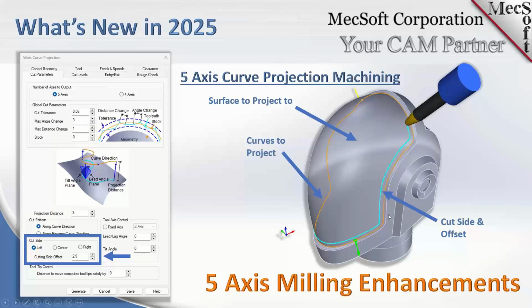And this method is used on 5-axis applications where you want to trim material from the edges of the part, or you want to clean up material on the edge of a feature in 5-axis. So again, this is the 5-axis curve projection, and this is in our premium 5-axis configuration, where you have all of the 5-axis continuous toolpaths available to you. And this one applies to the curve projection machining operation type.